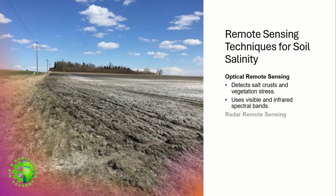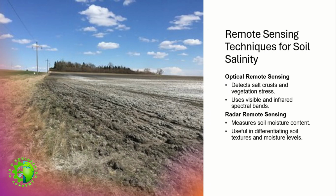Moving on to radar remote sensing, this technique is adept at measuring soil moisture content. Since soil salinity often correlates with moisture levels, radar sensors can provide critical data on the distribution and severity of saline conditions. These sensors are especially useful as they can penetrate cloud cover and provide data regardless of weather conditions, a significant advantage over optical sensors.